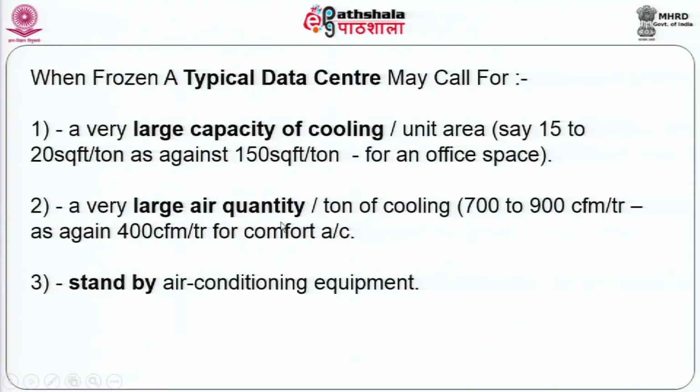Now in this kind of a loading, you would see that it is all basically sensible load. In other words, there is no moisture, it is all dry heat equipment, which does not contribute. For instance, now supposing you are doing an auditorium, you will find that there are people, you will find that you have to add fresh air. Now these two parameters add a tremendous amount of latent load, whereas in a computer room or a server room, data center, you will find that there is virtually no latent load. In fact, good computer rooms very rarely, except for 1 or 2 input output people, are occupied. So in such a scenario, it is only the dry heat which comes, it is only the sensible heat which comes, and the effect of this on the air conditioning is that you need a larger air quantity.